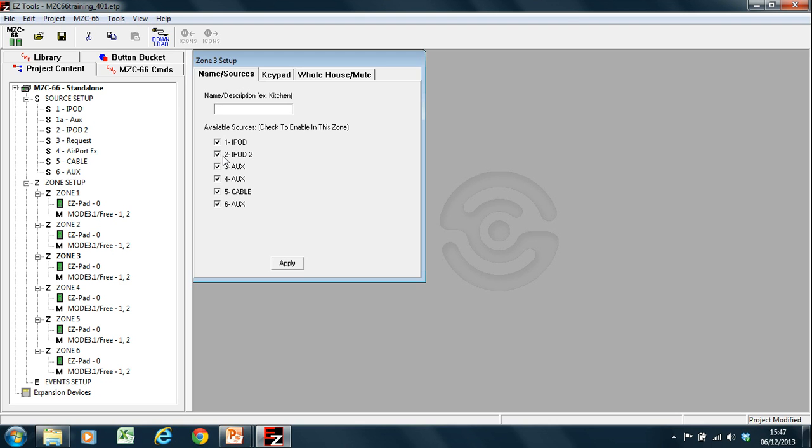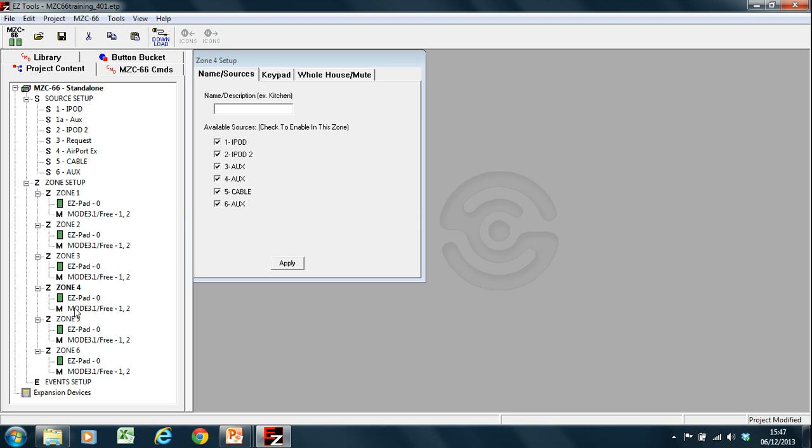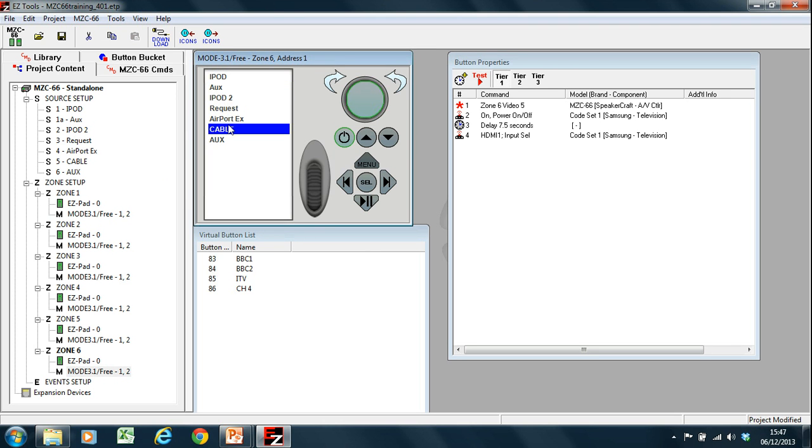You didn't see that I pasted, but let's rename it. So there's an R there. If I paste it, you'll see that it will wipe over that R. So it pastes it in. But now when I go to select a command, I can see it says zone 3. So I could just go ahead and paste the most common zone across all the zones. And now my programming is applied to all these keypads. And it's all correct. It's all for the right zone.